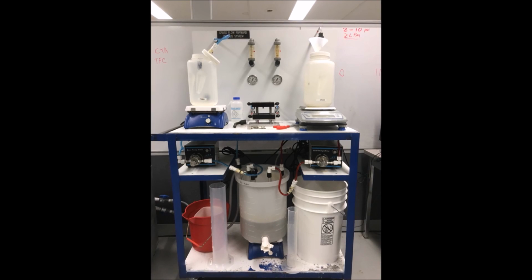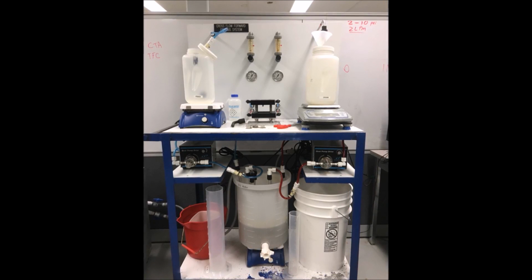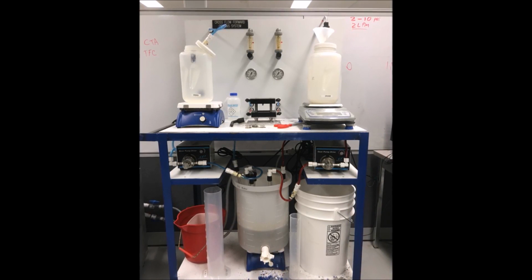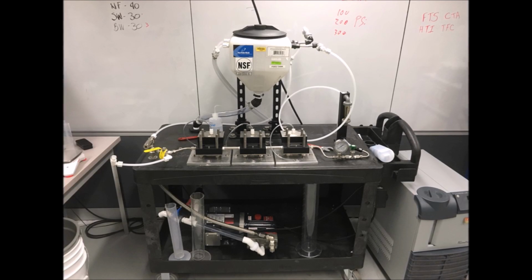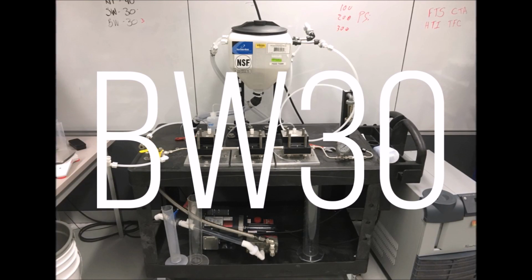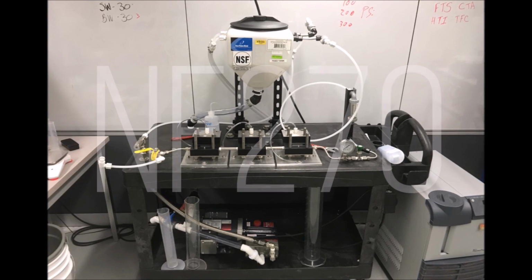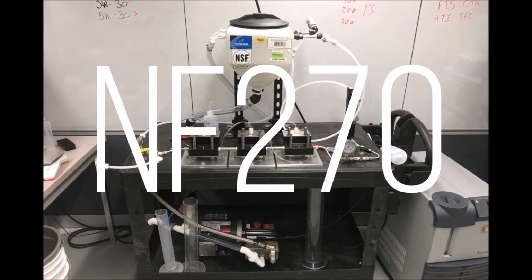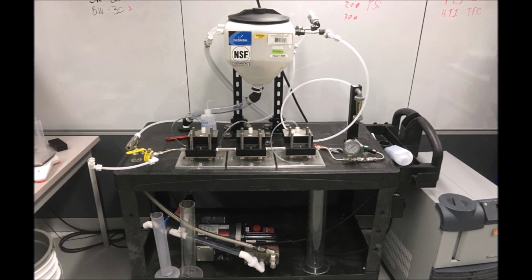Of the variables tested in the forward osmosis experiment, we can conclude that changing the pressure has no effect on the system, while changing the draw concentration greatly affects the fluxes. In reverse osmosis, each membrane had different properties, with BW30 being the best in terms of minimizing salt flux while maximizing water flux. However, the NF270 had the greatest overall water flux. Increasing the pressure also increased the overall water flux over all the membranes.